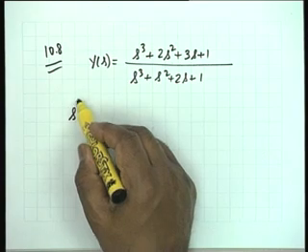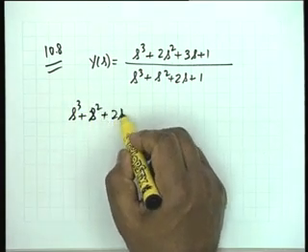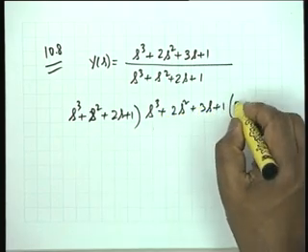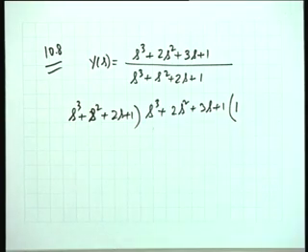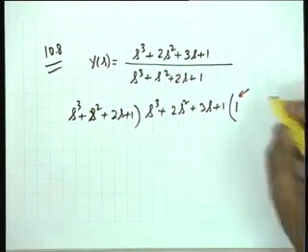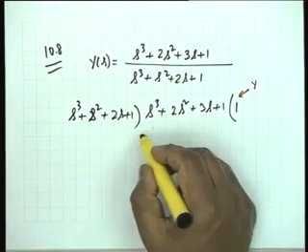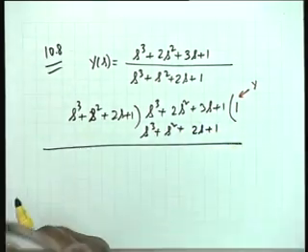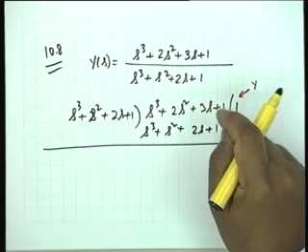The continued fraction is s cubed plus s squared plus twice s plus 1 into s cubed plus 2s squared plus 3s plus 1. So you take 1. What is the dimension of this quotient? Admittance. So it is y. We must keep track. I get s cubed plus s squared plus 2s plus 1. Now in continued fraction expansion, because we are going to realize a network, we are not permitted those liberties. Which liberties? Multiplying by a positive constant. No, because that will change the network elements. We are not allowed that liberty. If it was simply to find out whether it's Hurwitz or not, then of course you do whatever you like.